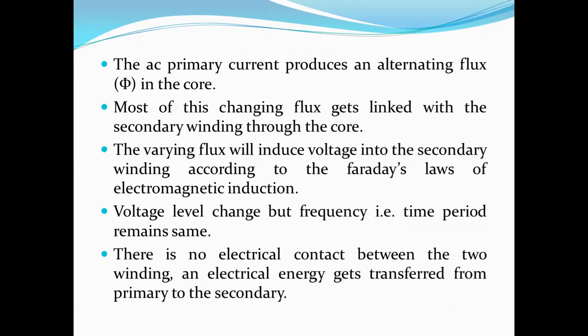Then in the secondary winding also, some EMF is induced. That EMF is known as mutual induced EMF. The varying flux will induce voltage in the secondary winding according to Faraday's law of electromagnetic induction. So the working principle of the transformer is Faraday's law of electromagnetic induction. The voltage level changes, but the frequency, that is the time period, remains the same.